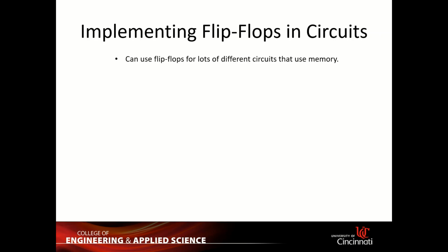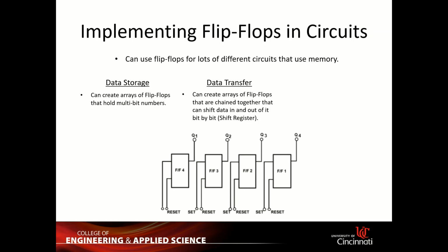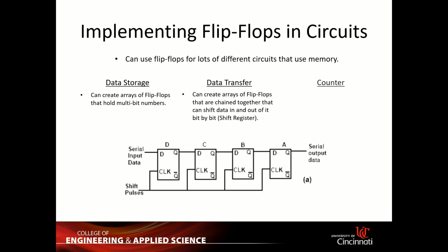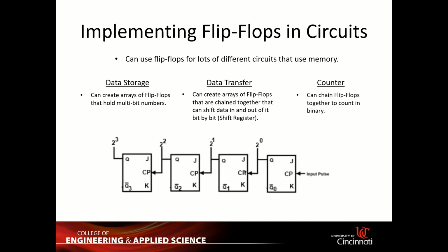Okay, so this last slide is very easy since we already covered the others. You can use flip-flops as a memory function. You can use them to store data. Remember that 3-bit binary adder that we did? We actually stored data in the registers, right? We can use them to transfer data. Same thing: every clock cycle we shift the data from our registers into the adder, then use the data storage at the output. And you can use them in a counter, so you can have some type of binary counter. That should be it for our PowerPoint slides.